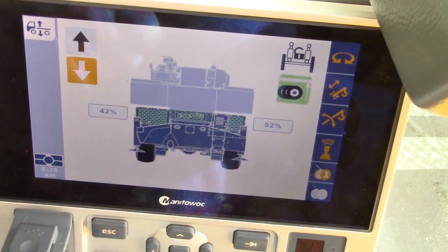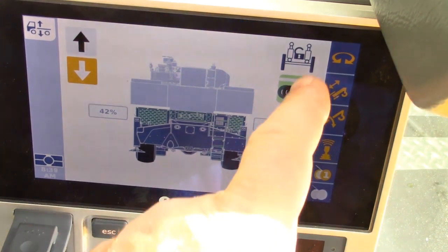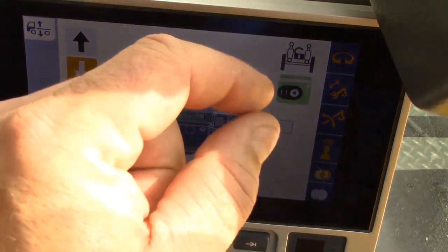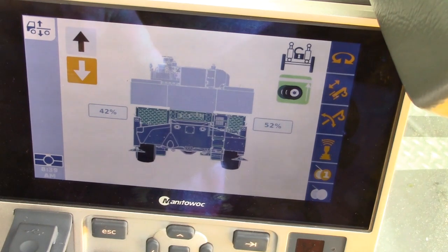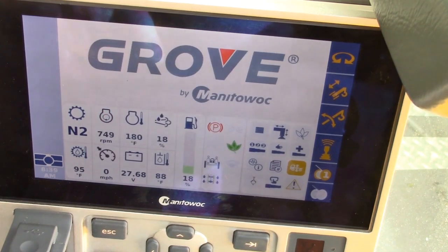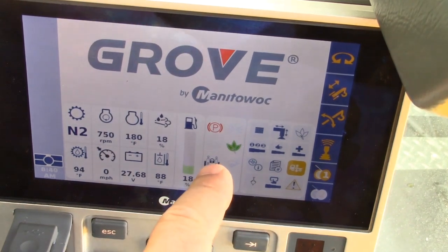As you go beyond the 3-degree tolerance left of or right of center, this symbol will then change on the home screen to a lock, representing that the rear suspension and axle oscillation circuit is then rigid. On the home screen, the axle oscillation circuit is shown here.